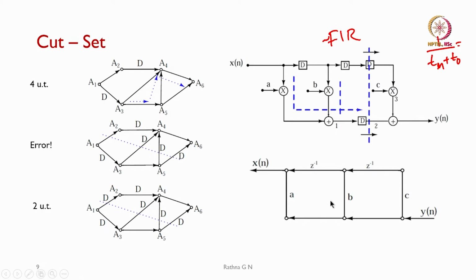We said to transpose the filter structure. This is how we did the transposed filter structure: input and output were reversed, and even the feed forward paths were reversed. By doing that, we call this a broadcast structure. So, x of n is broadcast to all the legs, and you will be having the delay in it, and then you will be multiplying. In this case, at each node you will be seeing the delay is 1 multiplication and 1 addition to get the output.